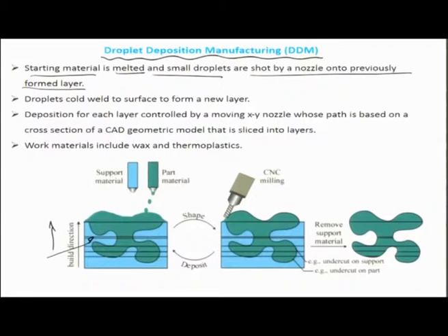So what you are essentially doing is you are having the nozzles typically loaded with two different materials which are molten. Okay, one is the material which would formulate the part, the other is the support material which would come off. Okay, the support material could typically be a wax layer again, which could be melted away, and so the part can get out.